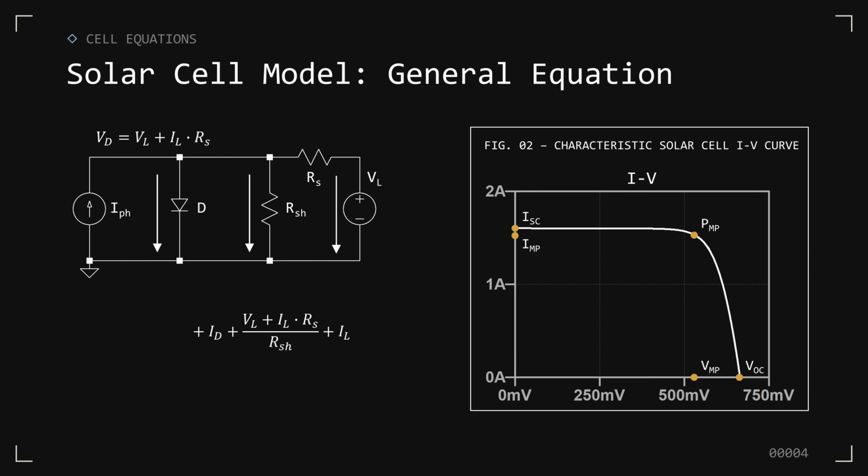The next branch is recombination current. In practice, people often describe what this branch represents as power left on the cell. Power the cell could have delivered, but the load condition did not extract. We'll momentarily leave it just as ID and replace it with the Shockley equation in a sec. So that's the third term in the equation.